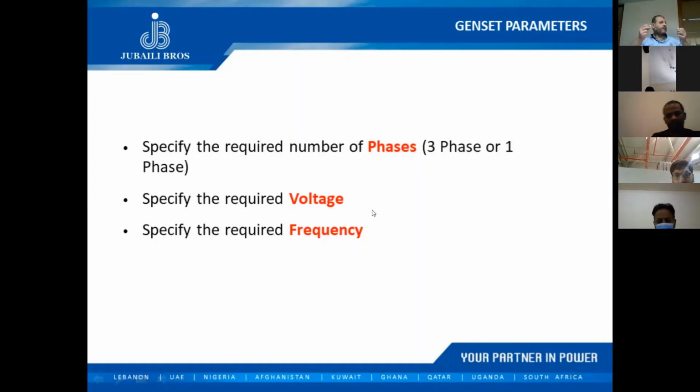We'll also have to remember that with a decrease in voltage at the same power rating, or at the same capacity, there's an increase in current, which means it affects our circuit breaker size as well. And it's also worth noting that for the same alternator capacity at different voltages, the rated power varies. It varies slightly, but it does.